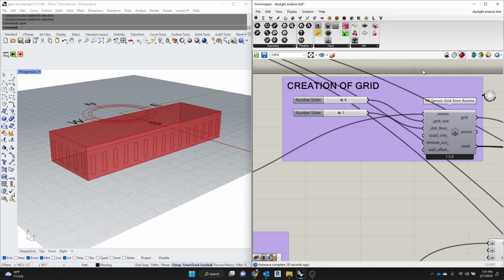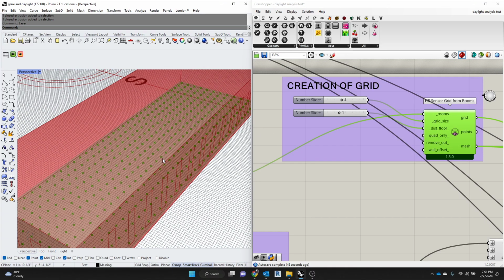So just so you know how this operates and how Honeybee works, maybe you remember this from the last time you looked at it, you need to imagine that it's going to test spots on the floor. If the room we were modeling was this one, and we had these walls built and these windows, imagine putting sensor grids at every single one of these spots at the carpet. At a certain hour of the year, we're going to report how much sun comes through and touches that spot, this spot, that spot, and so on. So you have to create what's called a sensor grid. You don't necessarily need to create it. It's already in here. I'm just showing you where it is.